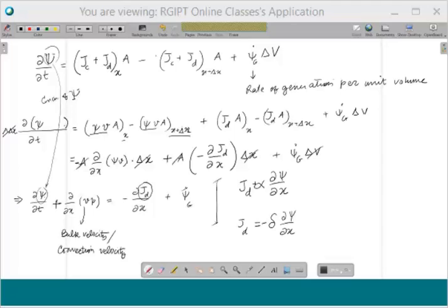So the positive side, psi decreases in the x direction, J_D will be directed towards positive x, since psi decreases in the positive x. That's like a negative concentration gradient. If you interpret big psi to be a number, then small psi becomes a concentration and this becomes the concentration gradient. This becomes mass flux or number flux. But in general, this can be identified with other cases as well, not necessarily mass, but momentum and energy as well.